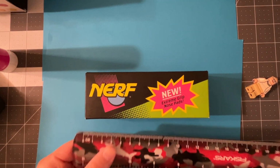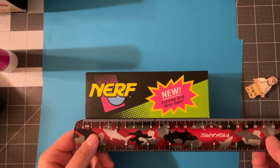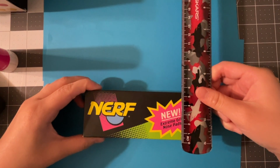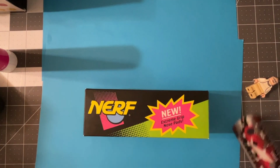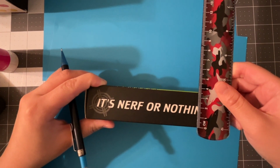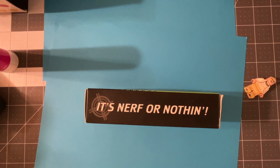Now that we know which views we are measuring, we can go ahead and measure it on our sunglasses box. So we can see that the length of the front view is 15 centimeters or 150 millimeters. The height of our front view is 50 millimeters. And on our top view, that width is 35 millimeters. Now that we know what our dimensions are, we need to put them on our drawing.